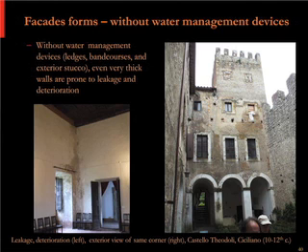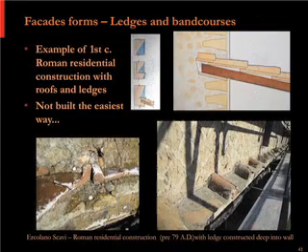And it's an example of a building, an extreme example, I think. So this is a castle in the area outside Rome, medieval, 10th to 12th century. It doesn't have any of these things going on. It was a very utilitarian type fortification. So there aren't any ledges, there aren't any band courses. There may have been plaster, which would have reduced the surface area of this rough stone at one time, but there isn't now. And so that's a photo of the same corner, exterior right, interior left. And you can see that although it's only 2.5 stories, they're taking on tons of water right at that point. So without any of those devices, this wall, and these walls are about 7 feet thick on this building, aren't doing so well.